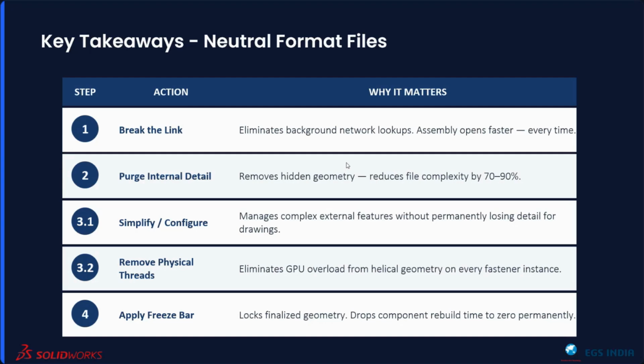We're also going to be removing threads, etc., and use cosmetic threads as an example to represent threads present in your bolt or axle, etc. And to make sure that all of these do not change and that SolidWorks does not calculate all of these features again, we're going to make use of the freeze bar present in your SolidWorks environment. By doing this, we complete the process and say that the geometry doesn't change. You don't need to recalculate the entire part or assembly. So these are the rules that in a simple way are used to optimize your step or imported geometry over here.